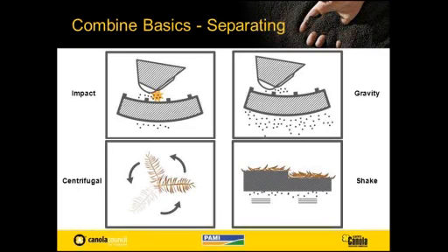And of course, we've used for years the old shaking method, which started from people in the early days using a fork to winnow the crop and sort of shake it and let the grain fall out, and the walkers. The problem is there that once they're mixed together, you get very little separation. If you can keep the grain and straw separated as it shakes, then it'll separate. But once they're mixed together, it's not nearly as effective.